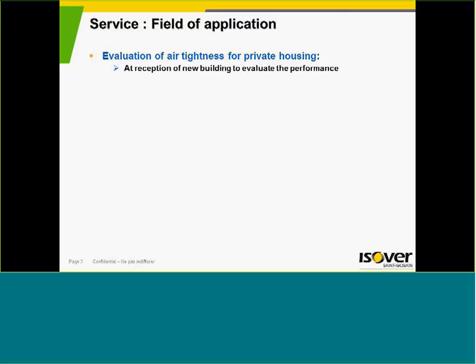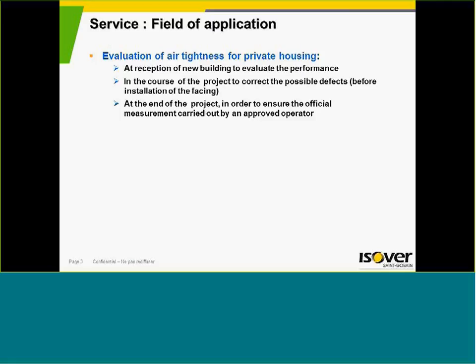And that is why this evaluation of airtightness is realized for private housing, at reception of new buildings to evaluate the performances, and in the course of the project to correct the possible defects before installation of the facing. Because it costs more to do the construction another time in comparison to correcting the project before the end of the construction.